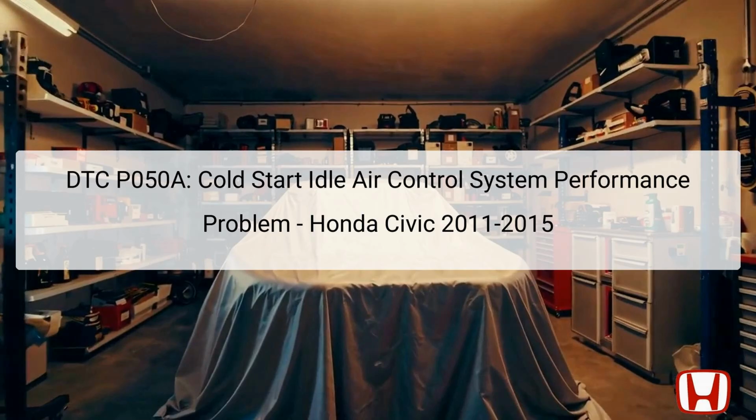It typically affects components like the electronic throttle control (ETC) system, the mass airflow (MAF) sensor, and the intake air temperature (IAT) sensor, which are critical for regulating the engine's idle speed at startup. The IAC system regulates the amount of air entering the engine while idling, especially crucial during cold starts when the engine requires more air to maintain optimal performance.